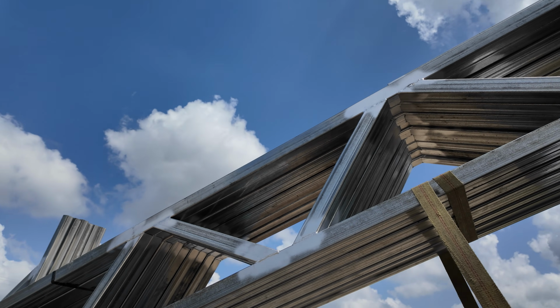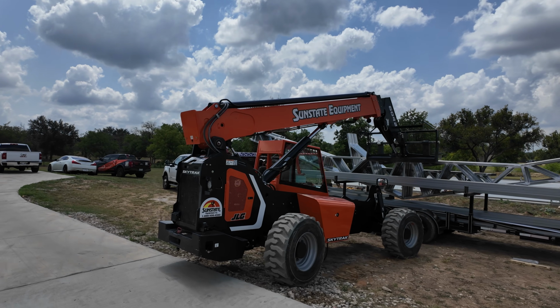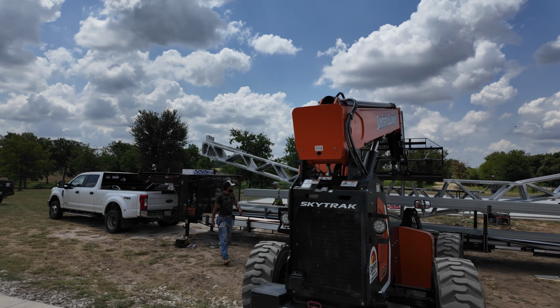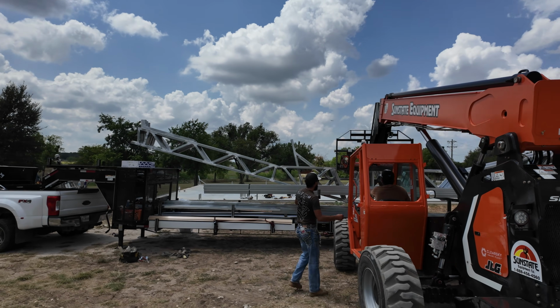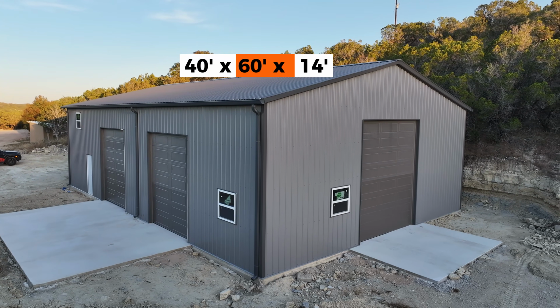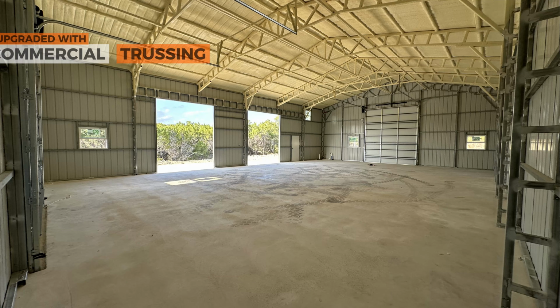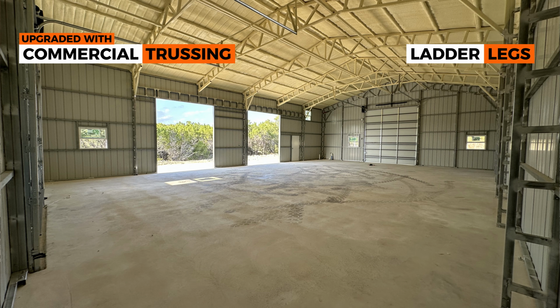It means we need extra materials, extra labor, and we will have an equipment charge in your quote, right? These trusses are very heavy, so equipment is needed. Aside from that, we have 14 foot in leg height. That's pretty tall. So again, Pack, we're looking at the building alone, 40 by 60, 14 foot in leg height, standard 3/12 pitch, vertical panels, commercial trussing, double legs.